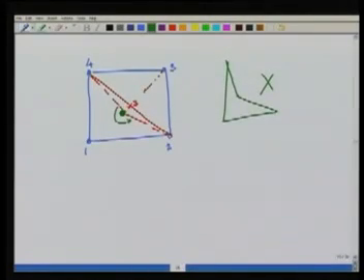We can always convert it into two quadrilaterals that are convex, that is, the angle is certainly less than or equal to 180 degrees. We do not want quadrilaterals with very large or very small angles, such as needle-shaped quadrilaterals. Generally their performance will be pretty bad.